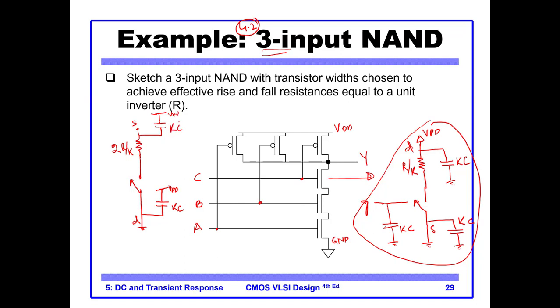So this is VDD, and then on the gate side we have the gate, and then we have the capacitor connected to the ground. So note the difference: for a PMOS, all the capacitors are connected to VDD because of the N-well.